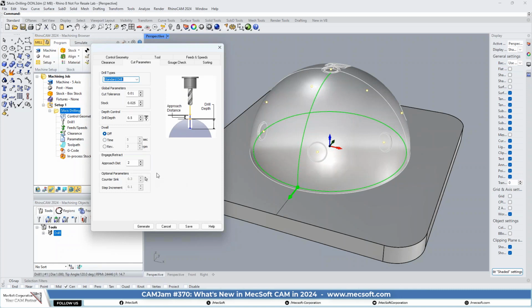Everything is basically the same in this dialog. The tool is lined up. Excuse those pop-ups, I forgot to turn them off. The tool is lined up on your hole, and it does the same thing in 5-axis. It aligns itself at the hole and cuts the tool depth. Everything in this dialog is virtually identical to regular hole making, so there shouldn't be any confusion about how this works.